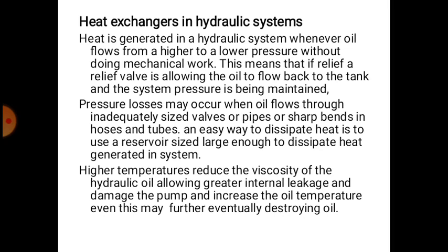Hence, temperature control is an important factor to be considered to maintain the performance and efficiency of the hydraulic system at its maximum level. Temperature control can be achieved using heat exchangers. Although design and circuit have considerable effect on the fluid temperature, heat exchangers are sometimes required to maintain the operating temperature, which is critical, or when the system cannot dissipate all the heat generated. The three common types of devices used for maintaining the operating temperature of the fluid are heaters, air coolers and water coolers.